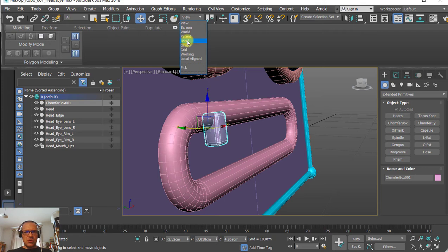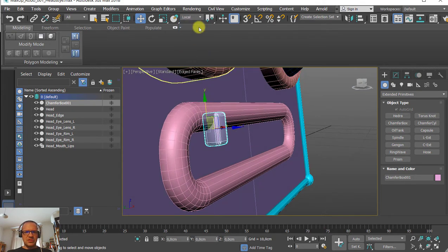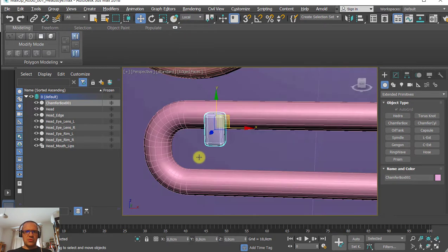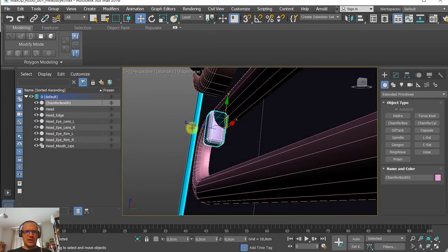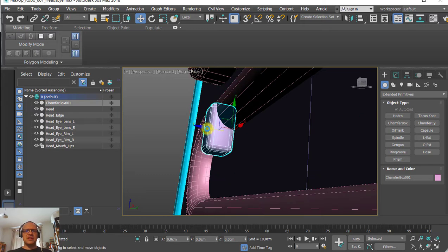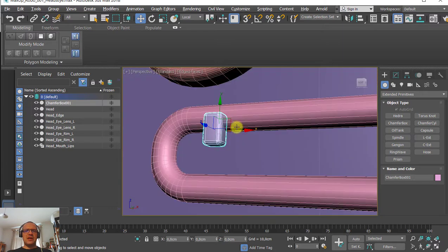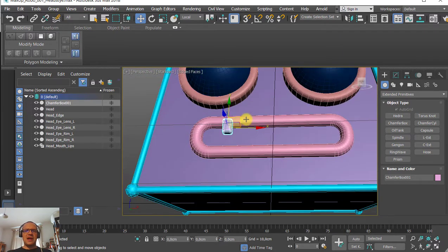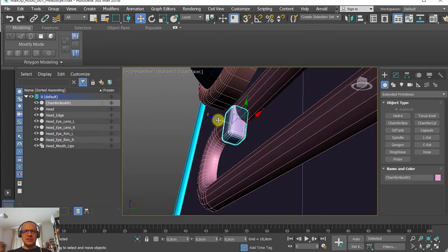So local mode is selected, and can you check? So this is what happens. Just hold on, look at the screen. By default we are in view, and I'm switching back to local mode, and local mode will change things, and now the coordinate is shown absolutely related to the object. So what does it mean? If you start moving while this mode is active, you will still remain on the surface, okay? So you can easily just sink in, pull it out.